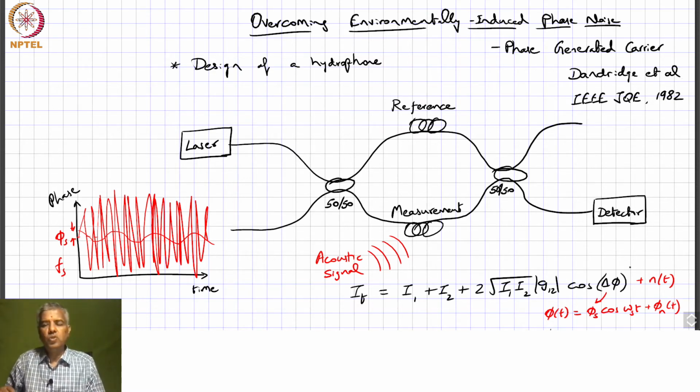And what did we use to pick up our signal in the presence of this strong noise? We used lock-in detection, right. So, we modulated the laser intensity at a particular frequency, and then at that same frequency we were using that as a reference and beating the signal that you got from your detector, and then we were trying to extract the signal in the presence of a strong noise, okay. So, that is what we did previously.